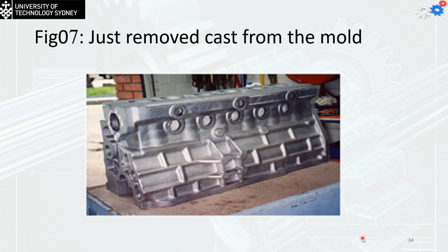So after we finish that, we just expand the mold, and we take the engine block out. So the core inside the engine block has been removed by the vibration process. It's adding the vibration, and this will cause the core sand to separate from each other and be destroyed, and then we can take it out. And then we're going to use the air blower to clean the engine cavities 100%.